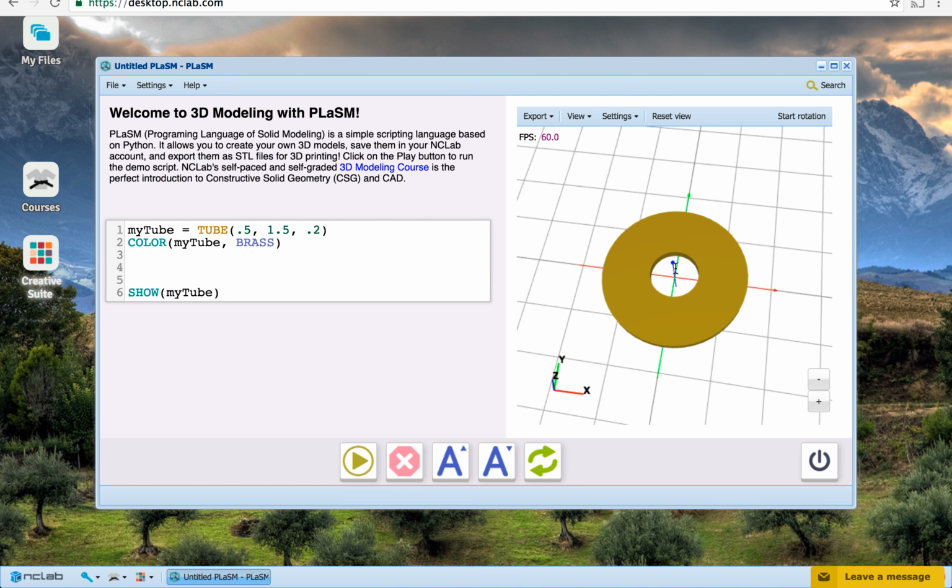It then creates this axis perpendicular to the main axis, which passes through this point and splits the object there. It takes three parameters. The first is the object we want to split. The second is this point on the main axis that we want to create our splitting axis through. The third is the all caps X, Y, or Z, which specifies the main axis that we're going to use.